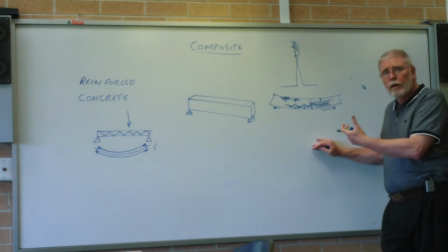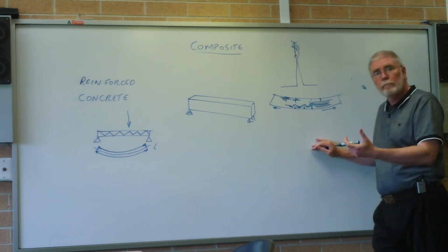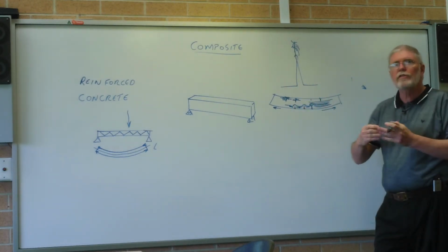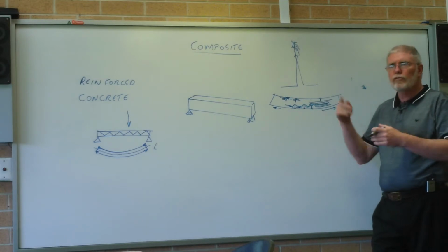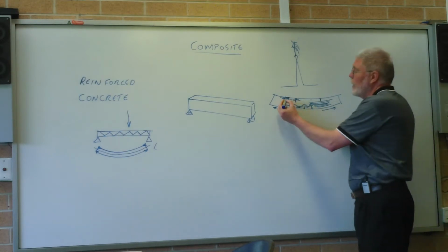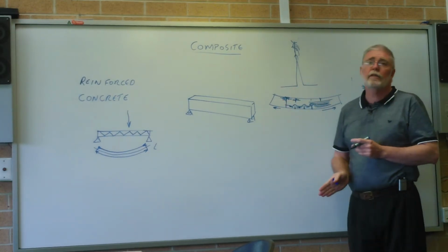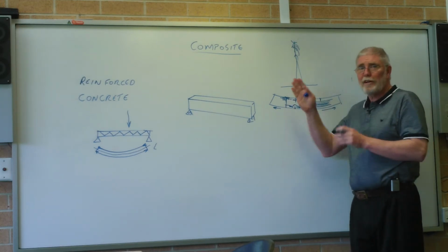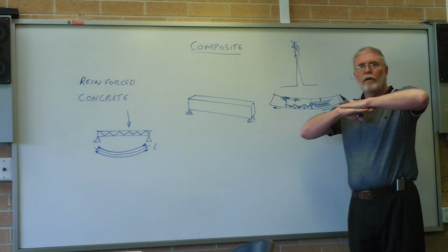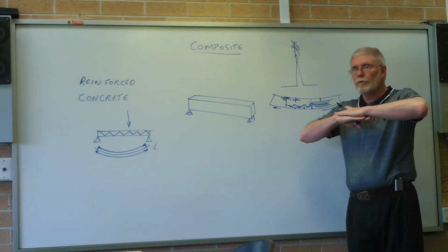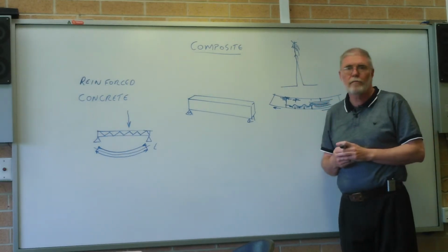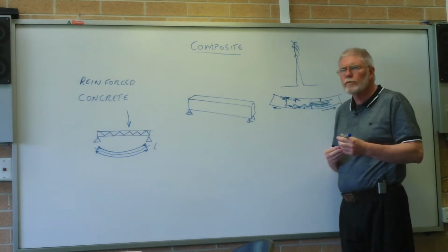Hence, these types of materials have strength in compression, but not in tension, because the tension is opening the cracks up and making stress raisers. The cracks in compression are being closed. It's just like saying, well, I had two bricks and I could have a completely straight cut across there. That's a large crack. It's just completely cut. Leaning on each other, it's going to be fine. As long as it's compression, it's going to be fine. I don't really have to worry about it. But the moment I start loading it in tension, they're just going to fall apart because they're obviously not connected anyway. Should make sense, should be perfectly logical.